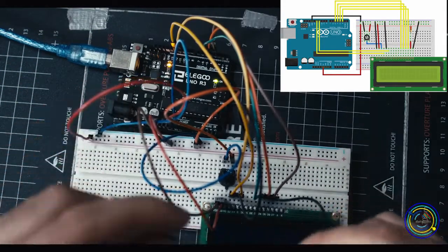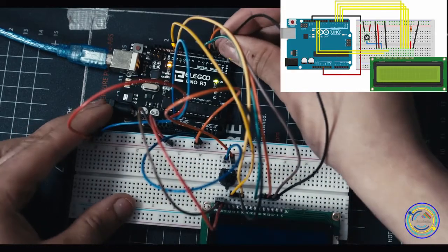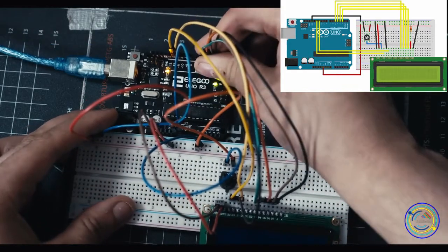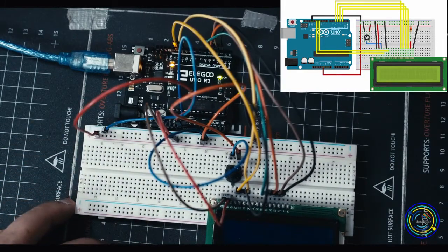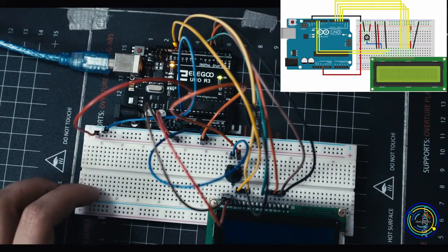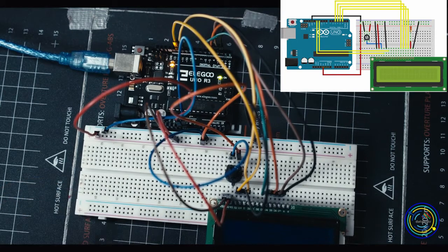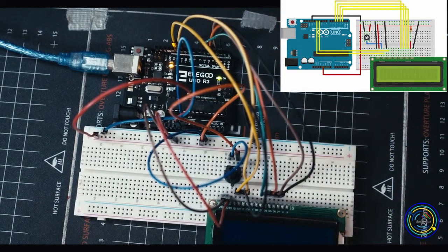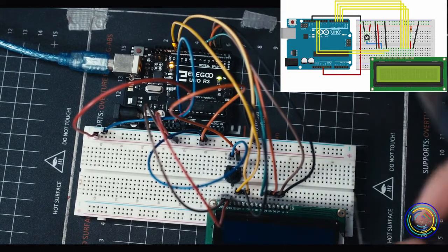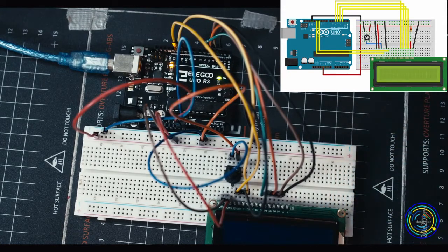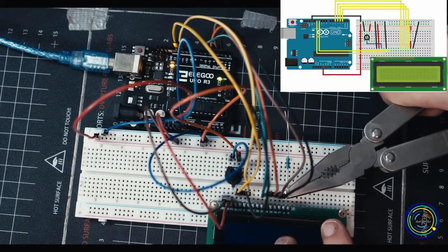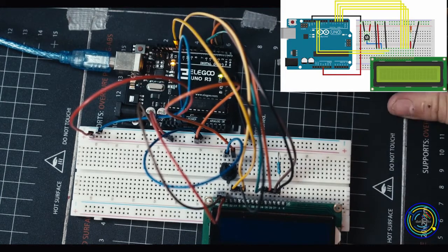The next one's in. Definitely recommend looking at the diagram and coming back to your Arduino and making sure that everything's lined up and good. Then we're going to use our resistor finally. I recommend you take pliers and use the pliers to shove in that metal pin because it bends super easily. So our resistor is going to be plugging into the second to last port here. Not the most beautiful setup, but it's going to work.